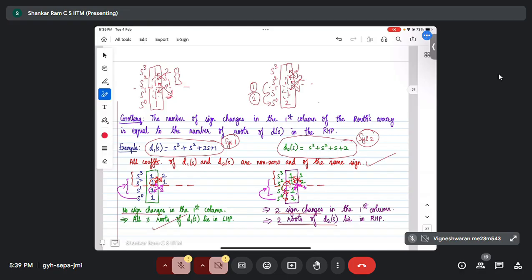Okay, so if this is the closed loop characteristic polynomial of system 1, then this is stable, right? Because all 3 roots are in the left of the complex plane. But if D2 is the closed loop characteristic polynomial of system 2, then the system is unstable. So that is the implication. That's how we use the Routh criterion for stability analysis, right? So in our course, we look at the distribution of roots, and if and only if the Routh criteria are satisfied, the corresponding closed loop characteristic polynomial will be Hurwitz, and the closed loop system will be stable. If not, it's unstable.